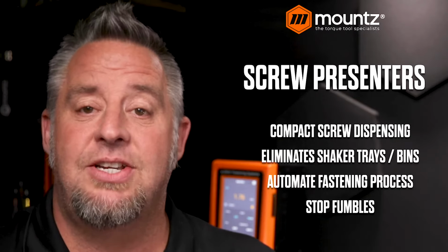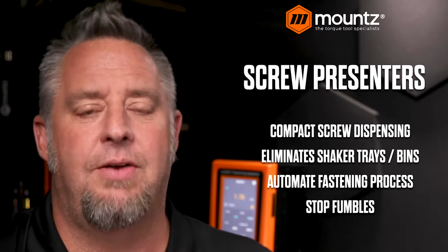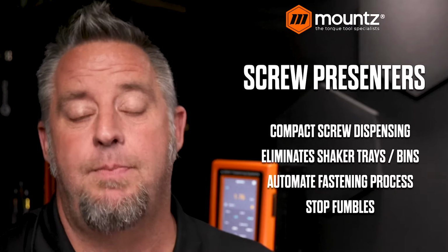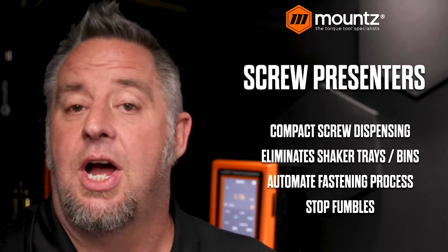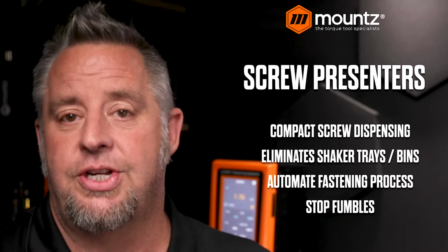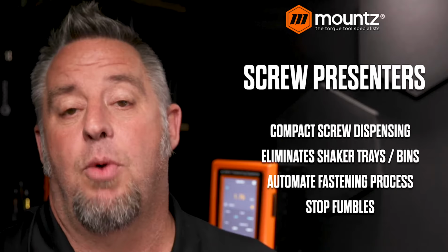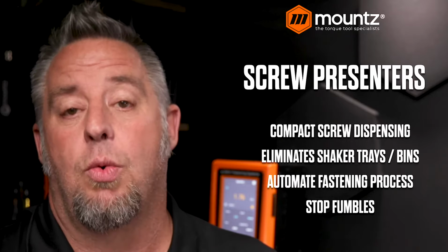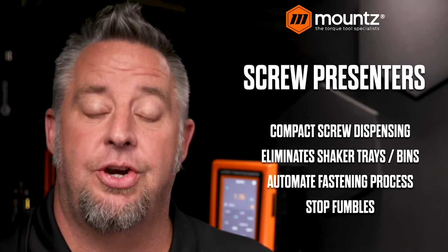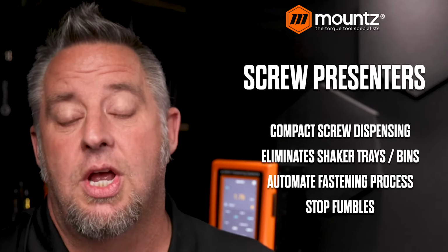In most cases, you'll see an improvement of about 50% in the cycle time when using a screw presenter versus doing the fastening by hand or with a shaker tray, where the operator needs to pick up the fastener, put it at the end of the tool, and run it.